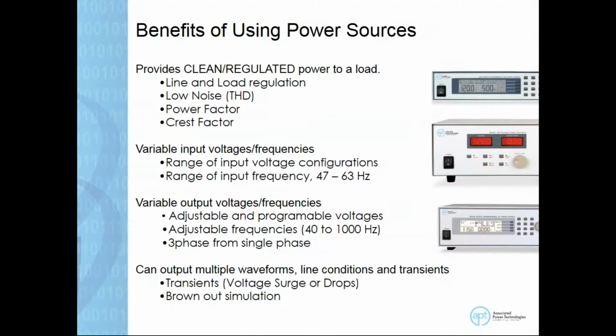When you have sensitive circuits, or when you're trying to measure sensitive equipment, you want to make sure that there's no interference from any other products on your line. So having a low THD is really important when you're using power supplies. Now, the majority of current generation power supplies are able to display the power factor of the load.